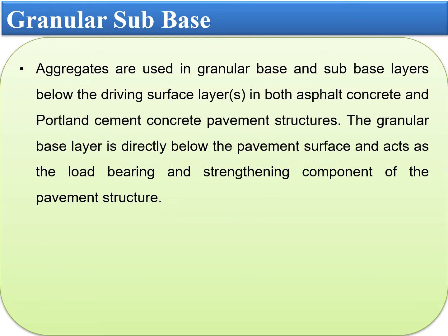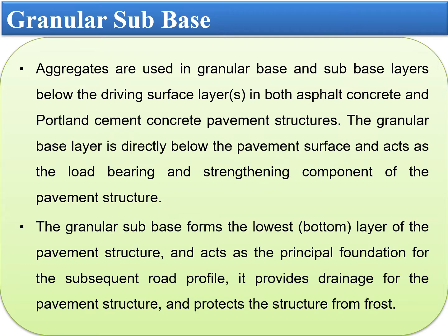As an introductory part, aggregates are used in granular base and subbase layers below the driving surface layers in both asphalt concrete and Portland cement concrete, or PQC, roads. The granular base layer is directly below the pavement surface and acts as the load-bearing and strengthening component of the pavement structure. The granular subbase forms the lowest bottom layer of the pavement structure and acts as the principal foundation for the subsequent road profiles. It provides drainage for the pavement structure and protects the structure from frost.